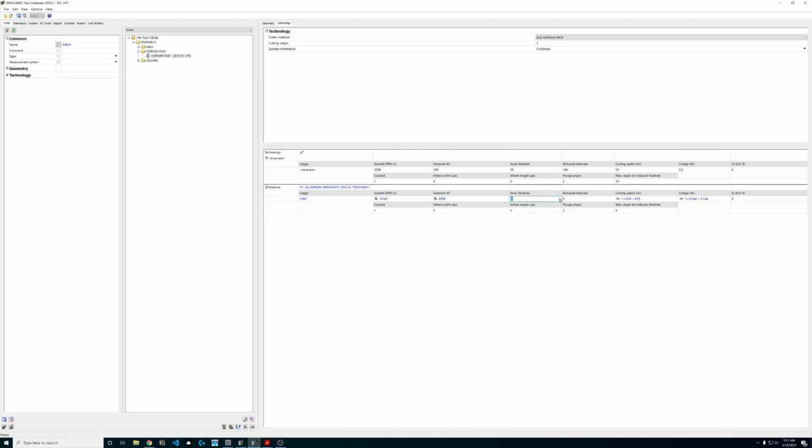Axial and reduced. Okay, this is something that you're going to have to play with. For us, the way hyperMILL's working, the axial feed rate might usually be the distance between the end of a G0 move and the workpiece. It's that distance. If you like doing things fast, then you probably don't want to use a reduced axial feed rate. As a matter of fact, sometimes I actually increase the feed rate because, especially in certain Z level operations,